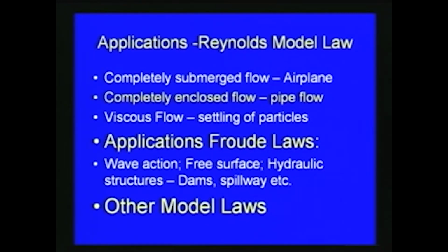Similarly, as I mentioned, when the Froude law or Froude number is considered, wherever the gravitational effect is more important, the Froude law is used. Cases like wave action, like estuary models or port and harbor models, for these models we can use the Froude law.